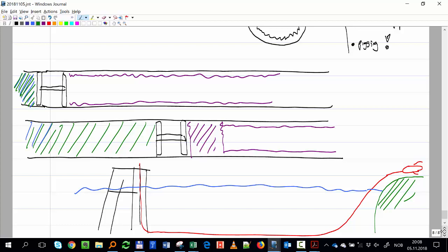Well, in this case, you have a flow line, let's say 50 kilometers. So you have one pipeline that is very expensive, $1 million for every kilometer of pipe. And then you forgot to pig it after a year, and then you try to send a pig, and you just cannot push all the things that are in front.